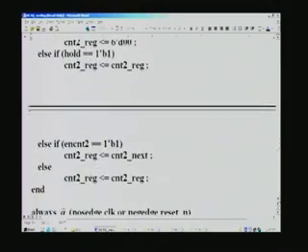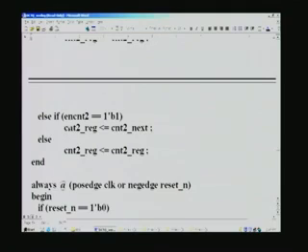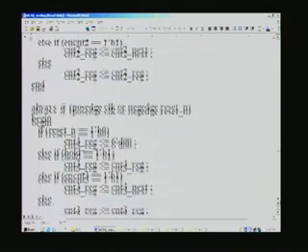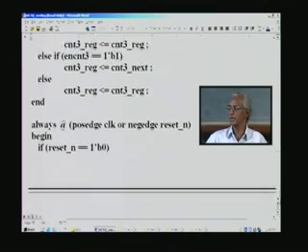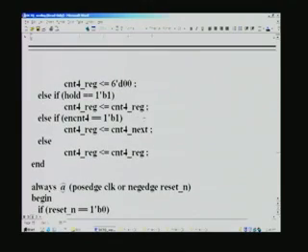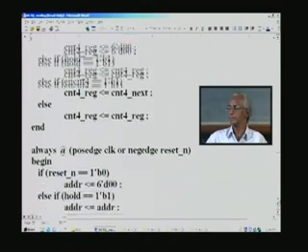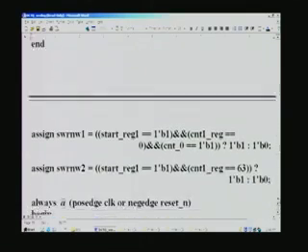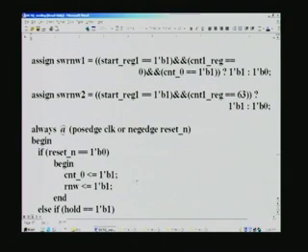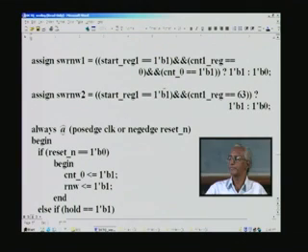You can see once again reset, hold, and we increment only if enable counter 2 is high, and same is the case for counter 3, and increment only then, and so also for counter 4 as well as for counter 5. So, here what we need is to differentiate between the very first block of processing and subsequent blocks of processing. That is possible only by having one signal here, and it is just a single bit.